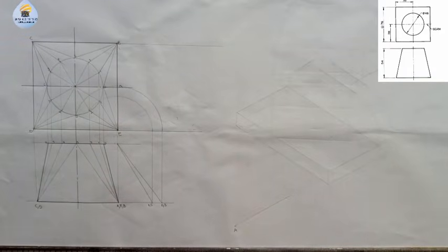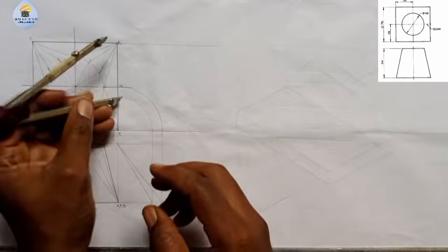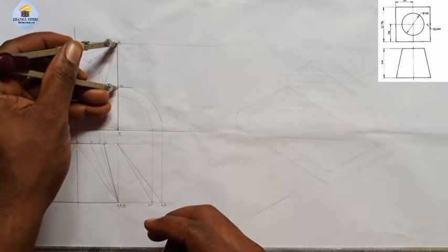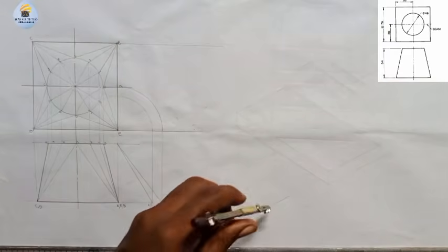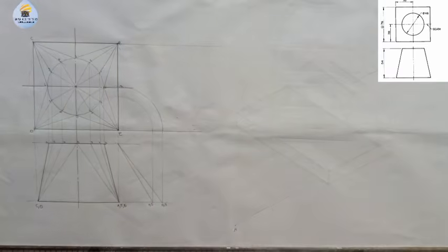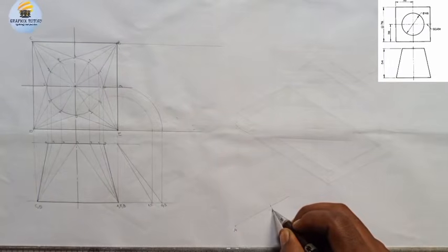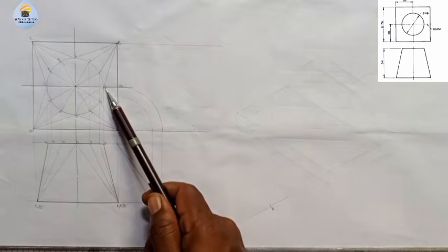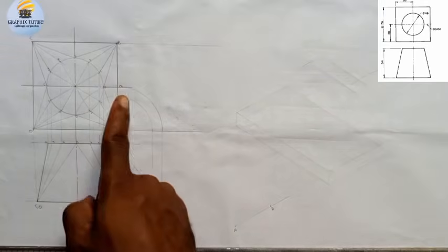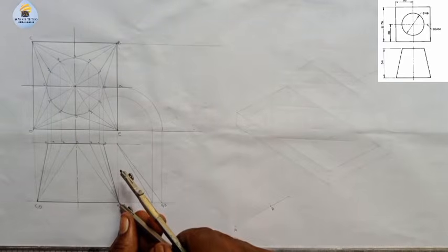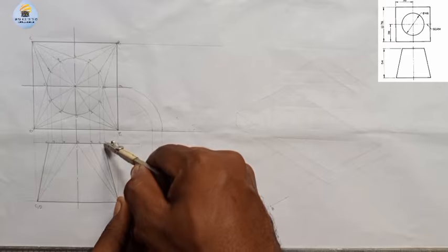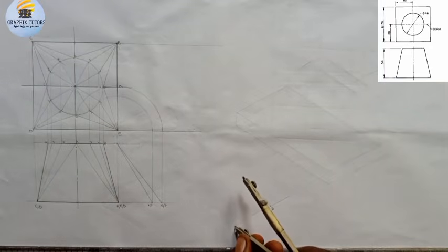So if I do that with the radius of AB here, you can see that I'll come to this point A, so my B is somewhere around here. This point here will be my B. Now what do you notice? We have B to point 0 and A to point 0. Going from A to point 0, this is not the true length here. The true length is here, A to 0. So I'll come here, I'm going to mark from A to 0, I'll come to this point, and I'll strike an arc this way.